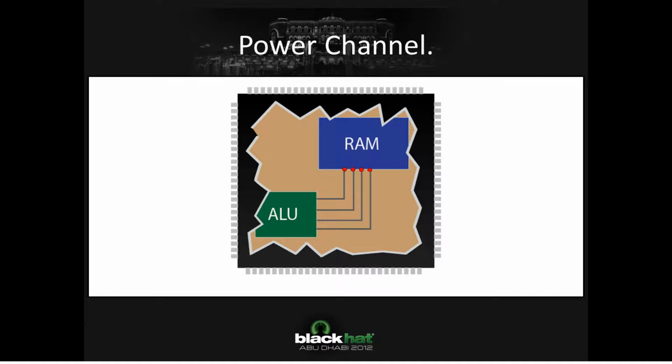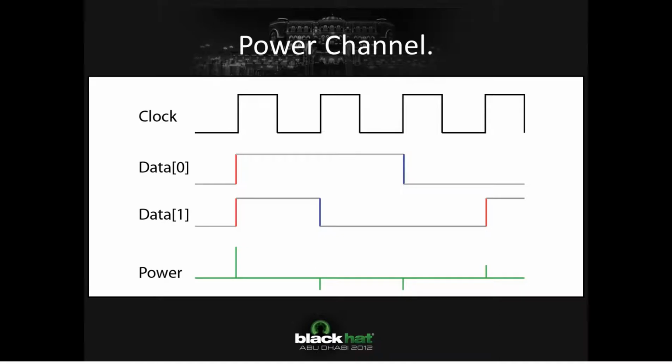How this data is sent is normally there's a clock that's distributed to everything. And the clock makes sure the device marches at the proper beat. On every rising clock edge, new data out, new data out, new data out. So this is sort of cracking the whip of the digital slave driver, you could say.